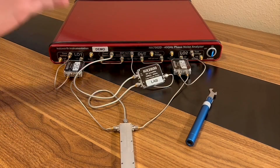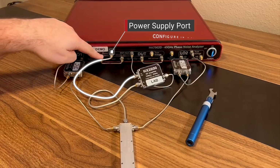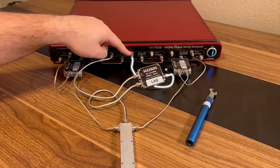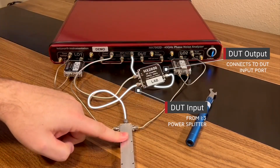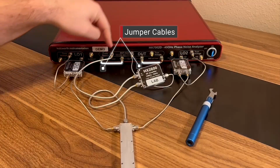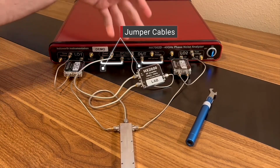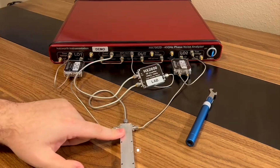In order to do that, there's a couple things. First we're going to power our amplifier with our power supply port, which I can configure within the GUI, and I'll show you that in a minute. But then the output's going to our DUT input, and our input's coming from this 1 to 3 power splitter. And I'll get more to that in a minute. I've also got the jumper cables connected here on the front of the unit from our DUT channel 1 input to our DUT input, along with channel 2 as well.